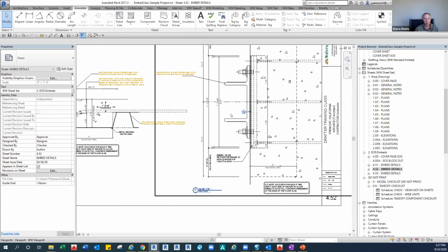And then it'll be like, well, Mike wants it this way, TJ says it's that way, Bobby wants it another way. So if you send me a little sample of what you want to do, because I would picture this detail, this is the embed drawing, that mat clip says mat clip, see schedule on floor plan, you know what I mean? Just the way your embeds say embed, see embed plan, right? Like you're not showing every embed in the shop drawings, and you're not showing every mat clip in the embed drawings.